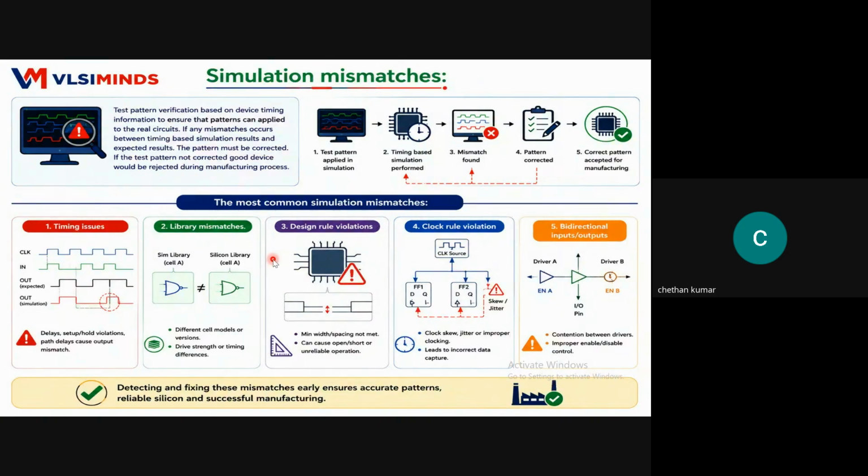Those also may create mismatches during your simulations. And real design issues may also come, because of some shorts or some opens in the design itself. Some unconnected nets or opens which are not solved during the insertion may also pop up during the simulations.